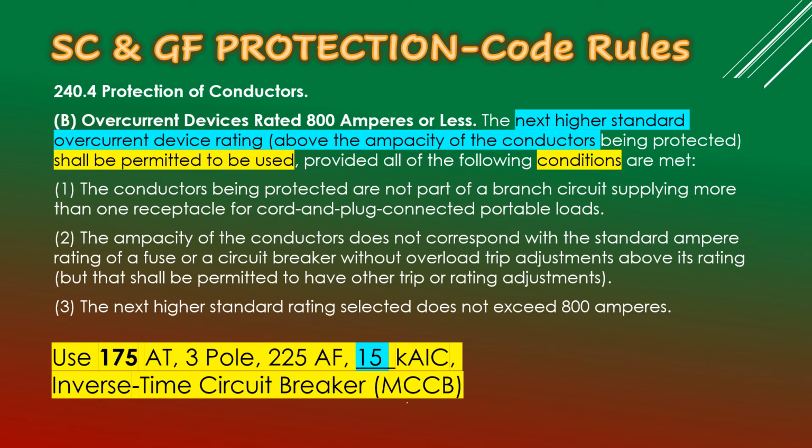3-pole, 225 ampere frame, 15 kAIC inverse time circuit breaker MCCB. So why do we use 225 ampere frame? This can be taken from manufacturer catalogs or product catalogs.